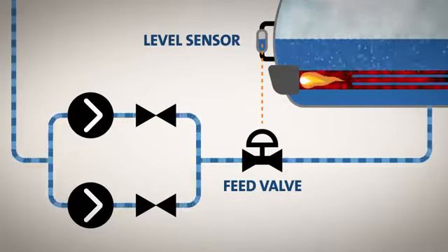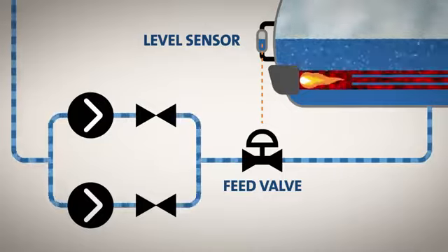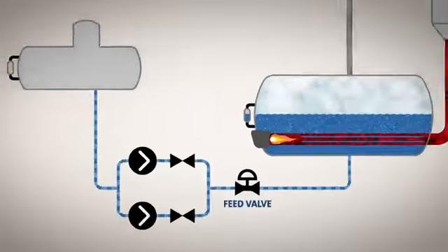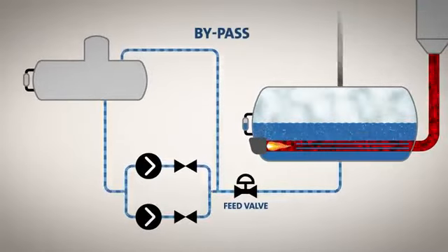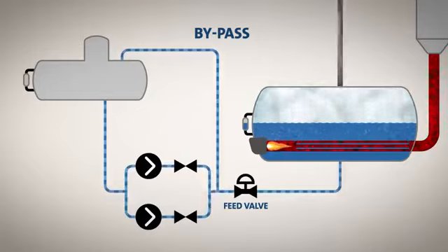This strategy, however, demands that the feed pumps operate continuously, and to prevent shaft seals from overheating, a bypass loop must be installed. This increases energy consumption, as the pumps now transport more water around the system than is actually needed to maintain the right level in the boiler.